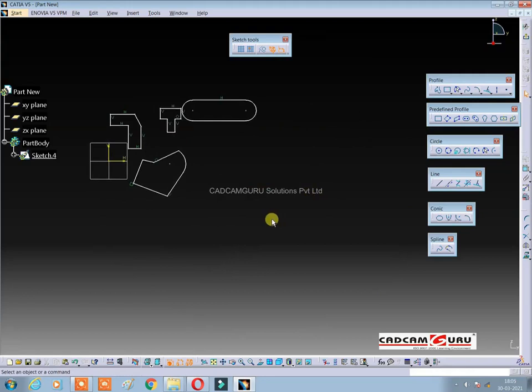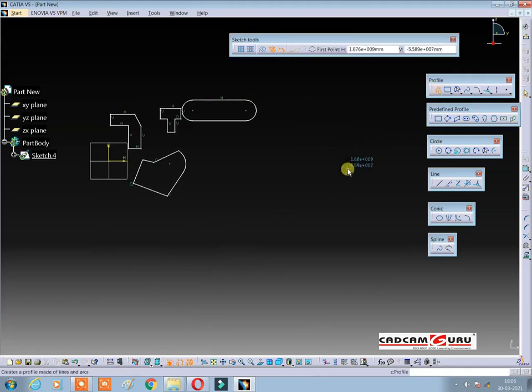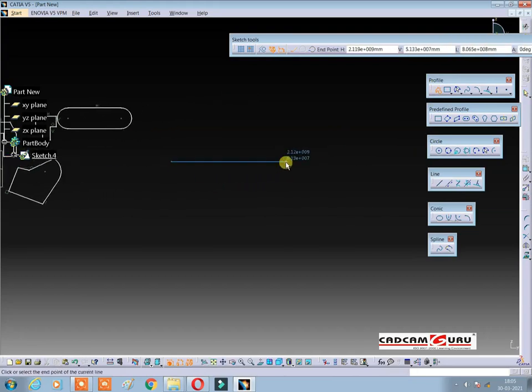If you find this method is not simple, I will show you a second method also, by which you can quickly create it, but the result will remain the same. Once again I will define the line. This time I am defining a whole line by defining 2 points. Now I will use this option, tangent arc, to convert this line segment into an arc.